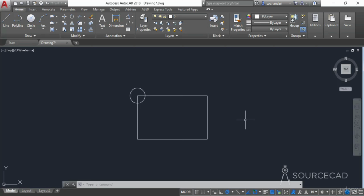In this video, I will tell you about move and copy tools of AutoCAD. So here we have this rectangle and we have a circle here on one of the vertices. Now let's say that we want to move this circle to the second vertex here. So for that, we can select the move tool from the modify panel. So select the move tool.